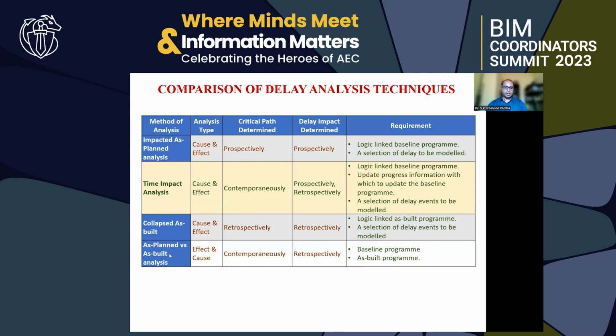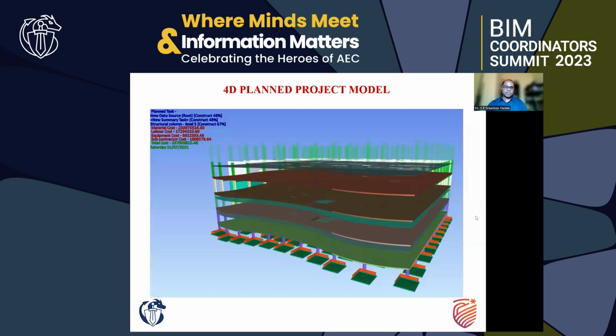But I also compared as-planned versus as-built analysis in the end. So in terms of analysis, I used a time impact analysis, but I also followed the basic requirements of as-planned versus as-built analysis. What I'm showing is the progress tracking. When the changes are implemented, I also tracked the 4D scheduling.